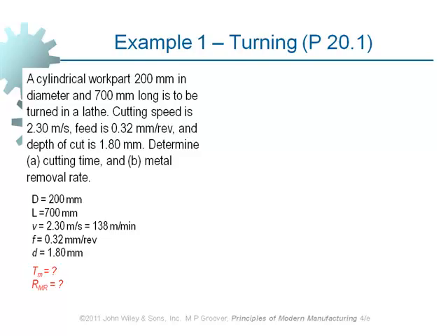Okay, this is what we are after. Which equation do we use first? First, we've got to compute the parameters to be used in the equations for the machining time and material removal rate. This is the first equation, right? We make use of this equation because V is given. Here I have done the unit conversion in the very beginning. It was meters per second, so I simply multiplied it by 60 to give us velocity in meters per minute. It's simple, okay? I have done the conversion at the beginning so that I put the right unit in the equation.